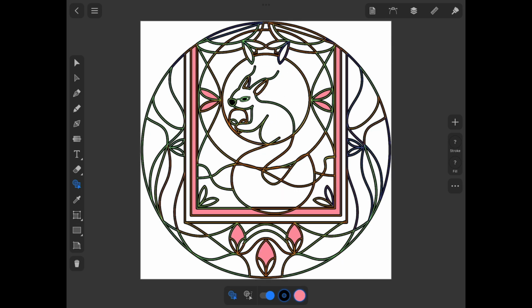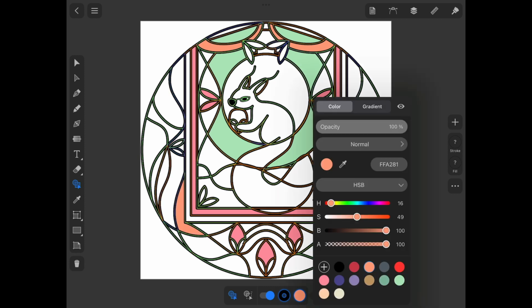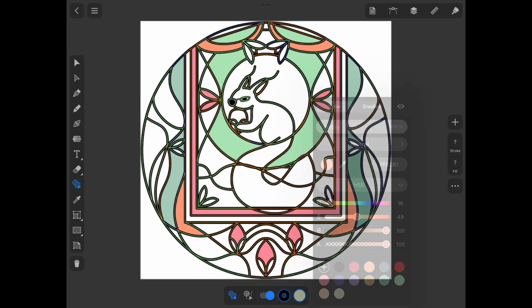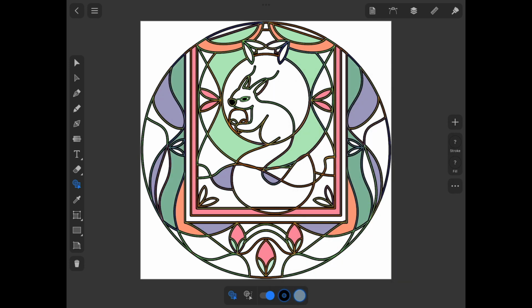Finally, let's create something nice and colorful. The Use Colors option allows us to use different colors for different areas. This makes it possible to color an image with the Fusion tool. Notice that I prepared a set of colors beforehand. You can do the same in order to stick to a fixed palette.